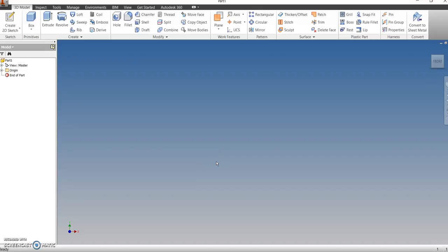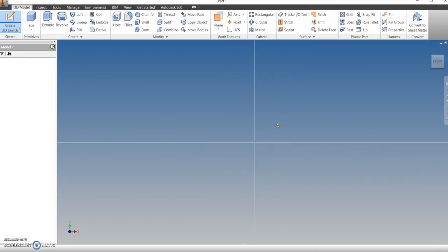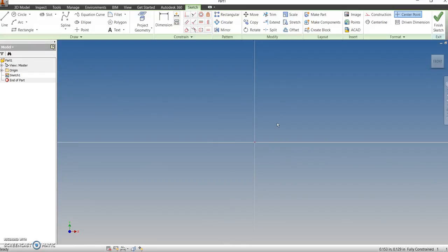And it brings us into Inventor, opens up Inventor into that drawing mode. Okay, and we're initially going to start in a 2D drawing environment. So once we get rolling, we want to basically select Create 2D Sketch. We're in a 3D model, but we're going to create a 2D sketch to get rolling first. And with this particular drawing, part 1 looks like an L laid down on its side. We're going to use this XY plane, this vertical plane right here that's selected. So I'm going to select that.